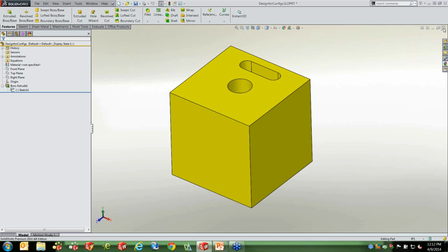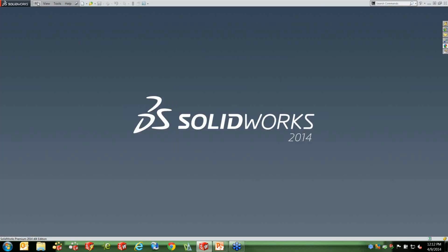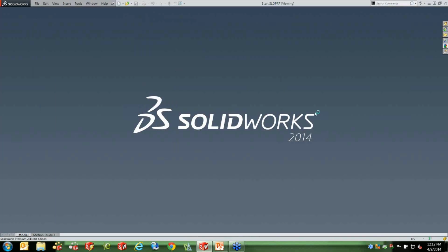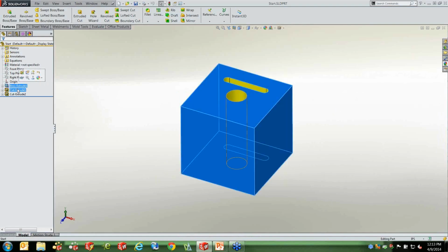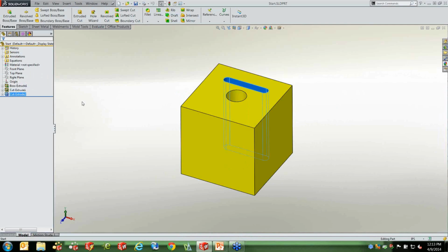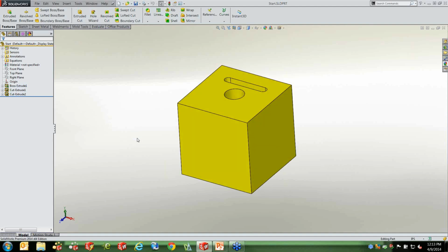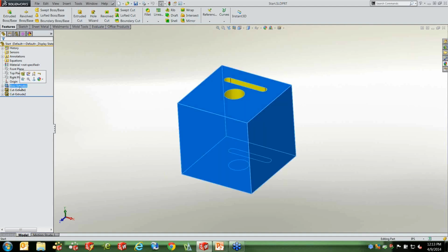Now, another approach to this, and the better approach in this case, is to build the part with each feature that you may control by basically turning on and off as separate features. In this case, this offers me a lot more flexibility to be able to do that. Now, renaming is important as well. So, we're all used to the ability to rename in the feature tree.